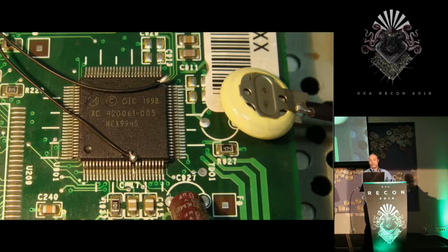So at this point, I have an ACP inside of a set-top box that I have an external battery connected to. It's still inside of the box and still working. So at this point, I can load up the pins with a lot of flux, put some hot air on it, and very carefully lift up the chip without letting the solder on the battery connections melt.